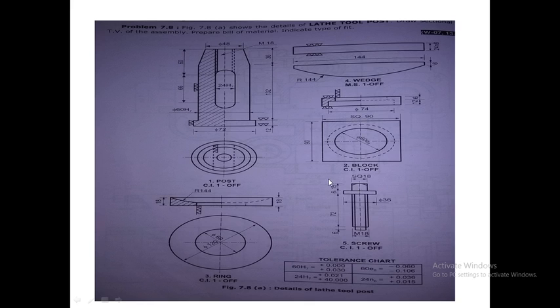Now the total height of the screw is equal to 15, the upper part, plus 6, this, plus 72, plus 6. If we add all the dimensions, we get 15 plus 6 is 21, 21 plus 72 is 93, 93 plus 6 is 99. So the total height of the screw is 99. But the lower part, of height 72 plus 6, that is 78, will go inside the post, whereas the upper part of height 21 will remain outside the post.